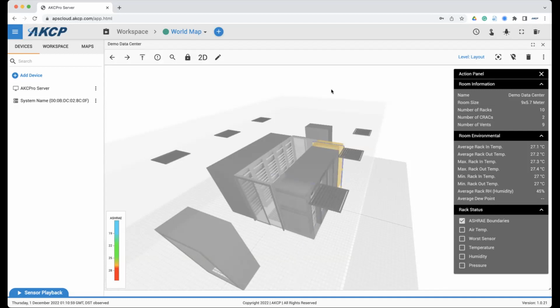I have a question about, you mentioned that you need the current to run the CFD model. Yes, the power readings. So I don't remember Gabriel showing the power when he did his model. Is that required, or is it just recommended? I believe it's required. I think, Gabriel, we have to have the temperature of the rack and the power, yeah? Yeah. We have either the power or the air velocity, because we have to compute the air velocity.